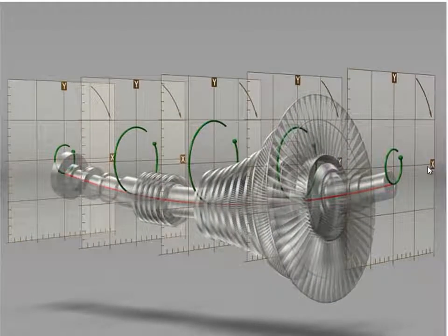There are so many details I'm leaving out, but just to give you a general idea, the orbit tells us what the center of the shaft is doing. So here we see this nice little orbit because it's moving in this small circular motion. More here, much more there, less and less, sort of similar, because that's what the shaft is doing, that's what the rotor is doing. Now we may not be able to put proximity probes in all these locations. I'm just showing this for illustrative purposes, but this is the orbit, and that orbit tells us, it may be